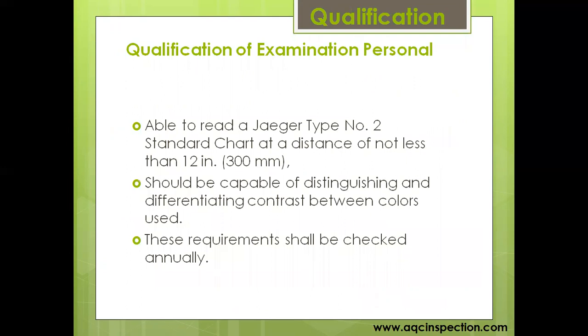The qualification for the person performing the liquid penetrant testing: he should have clear near vision test and color blindness test. And these vision tests should be performed annually by the employer.